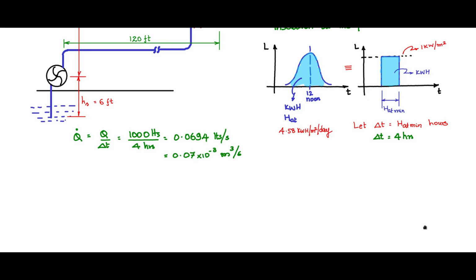So let me now make some space. Now all other parameters being the same, I will expect you to go through the same sequence of calculation. I will now point out only the difference. Here HF is calculated using the Darcy-Weisbach formula, F L by D into U square by 2G in meters.